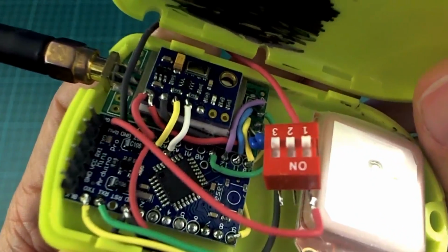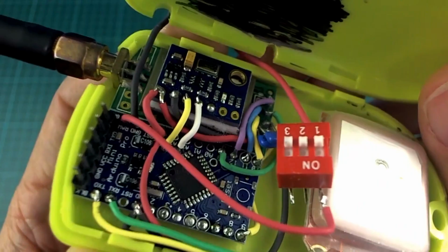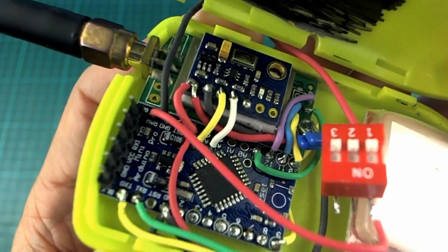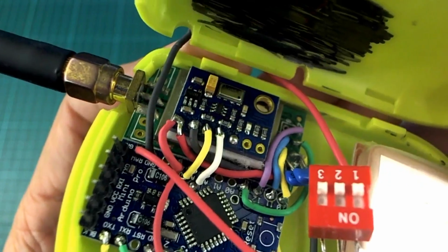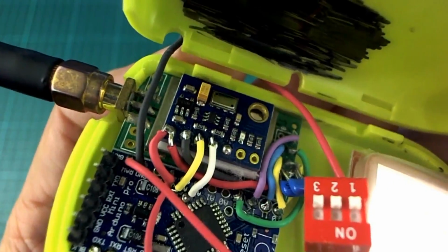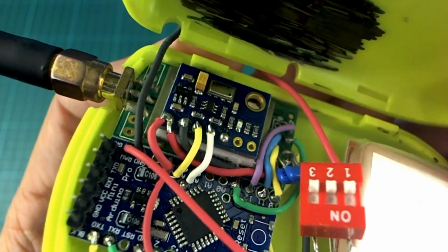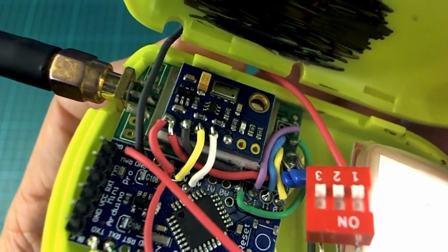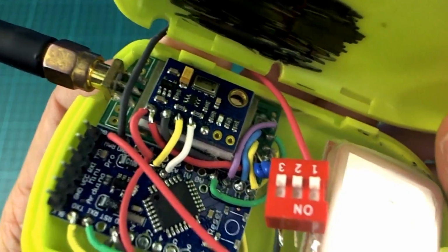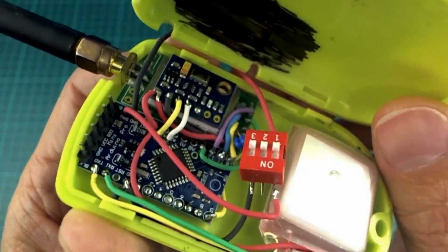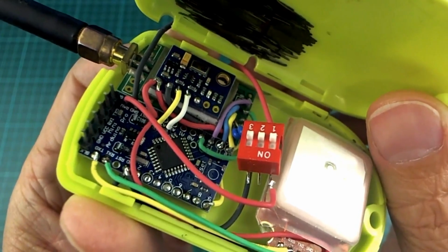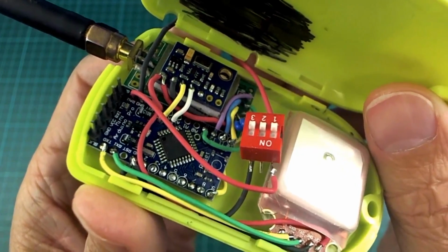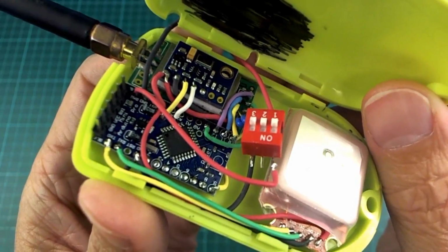Yeah, it must be, because there's no voltage regulator in here. So the 3.3 volt Arduino Pro Mini, and there is an MS5611 barometer. They are connected by an I2C connection. So this being a fairly advanced sort of undertaking, I'm not going to explain a whole lot of details about where all the wires go.